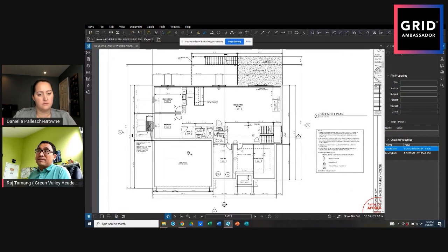So what I'm trying to say is, if you want a lot of doors and windows, you can do it, but it's not so possible with wood frame construction. With frame construction, there is a certain amount of solid wall you need in the house. But if you want everything glass, then instead of wood, we may have to use steel, and your cost is almost 5 times, 10 times.